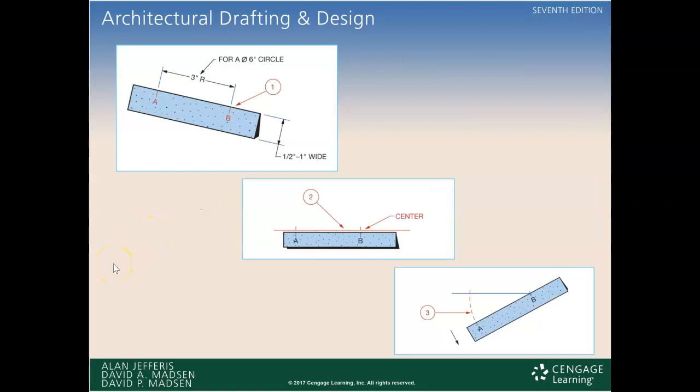This would be the trammel method, which is if you take a straight line, in this case a piece of paper, you label A and B, and to get the circle you divide half of that distance, the radius or whatever that line is going to be, hold down the center where B is, and then rotate that paper with the lead, of course, because you need a scribing device, and that is the trammel method. And woodworkers use this a lot, carpenters.